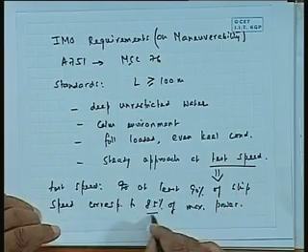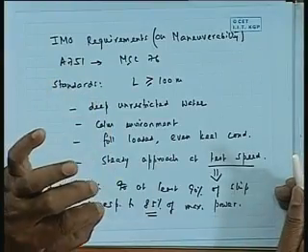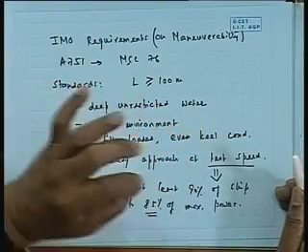You see what happened. You have a ship with full power. Sometimes if you give the full power, you will have a higher speed. Say the ship is designed for say 16 knot speed, but somebody will say that I am going to go at 14 knot speed always. But basically, it turns out that if you increase the speed, it has an effect on the turning abilities. So they specify that you must do this test at least at 85% of the maximum power.